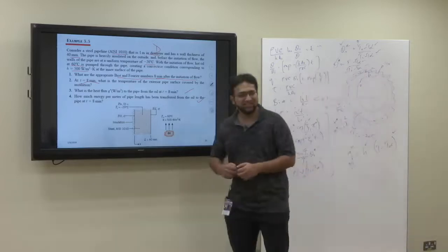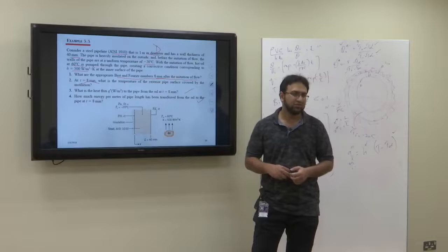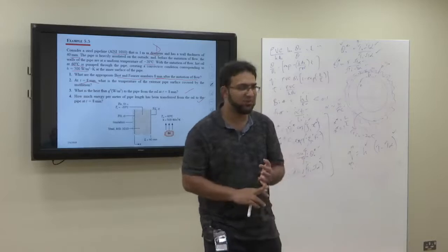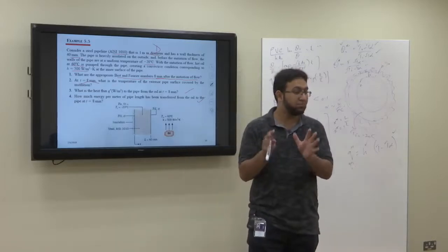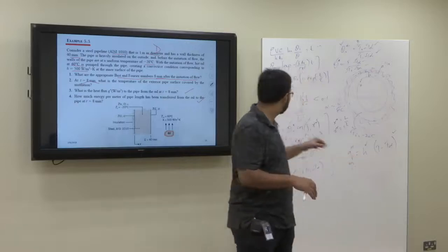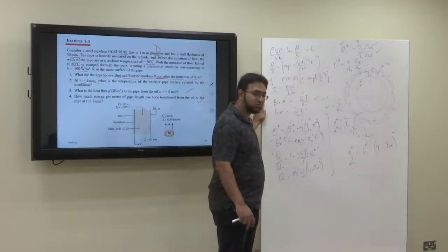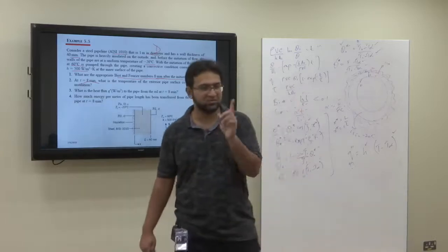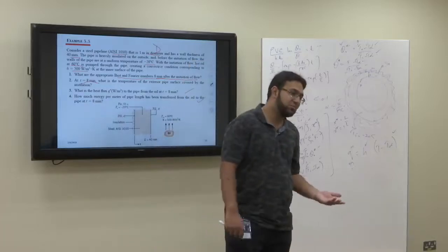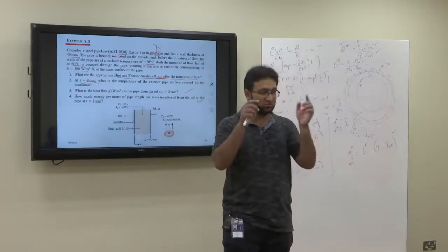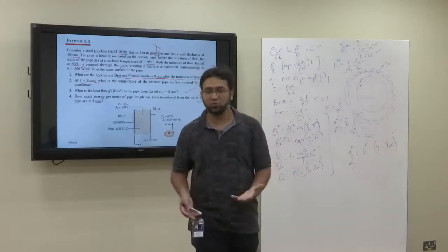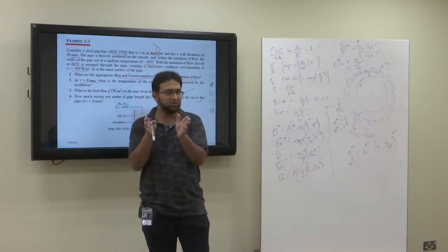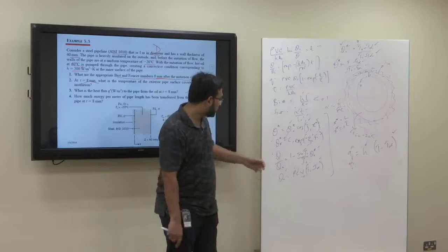So with this, we complete our chapter number 5. Just to summarize, we started with the transient problem. First we made an approximation, and the approximation made our life very easy. We got some formulas that are comparatively easier to use, and we solved a problem based upon that approximation. But the approximation requires Biot number less than 0.1. If the Biot number is not less than 0.1, we cannot use that approximation. Then special effects will be there, and the problem becomes more and more complicated. So we only solved a small case, the first approximation, only for the plane wall case, and we got these 4 formulas.